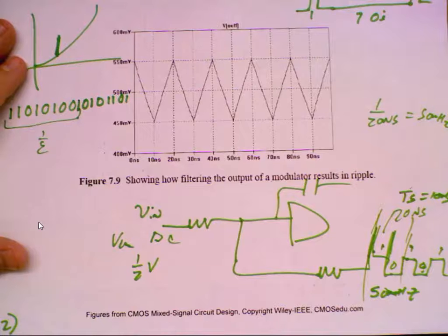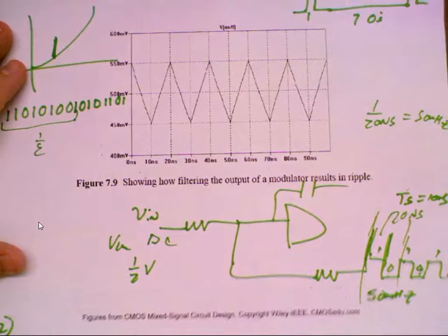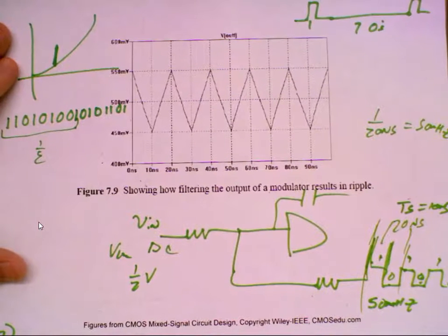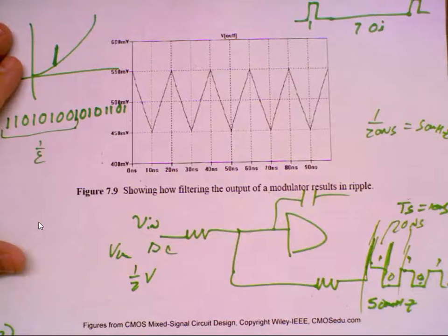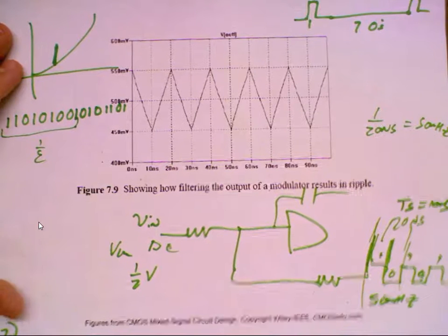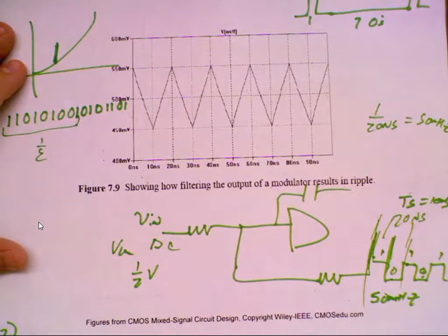Okay. So if we go second order, that's not an issue. If you do a second order delta sigma, it won't be an issue, unlike with a first order, because you're going to have various paths and they're not going to fully settle. So you're going to have non-repeating sequences, so tones shouldn't be an issue. Okay, are there any questions about that?